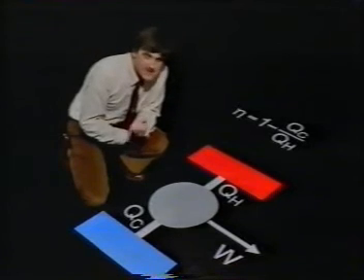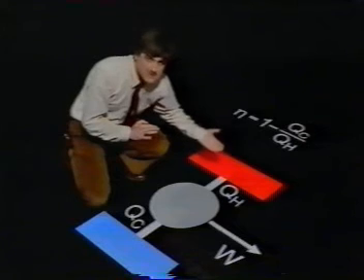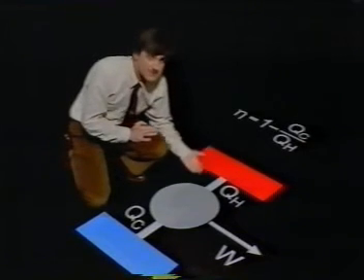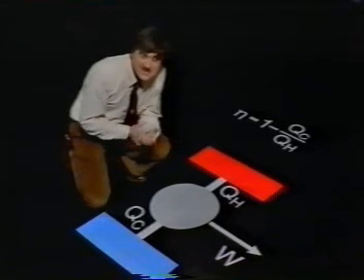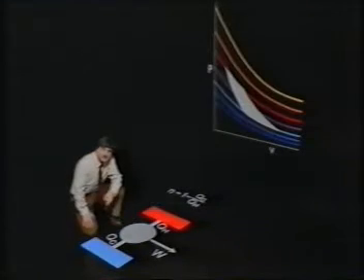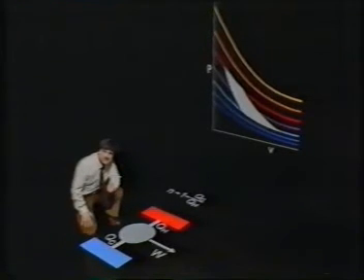And we use that kind of thermodynamic argument to show that only when the reservoir is at the same temperature as the working fluid can we achieve maximum thermal efficiency. That's the condition. And this is what Carnot realized when he invented the cycle, that any time that you contacted the reservoir and the working fluid at different temperatures, then you were losing some possibly useful work.